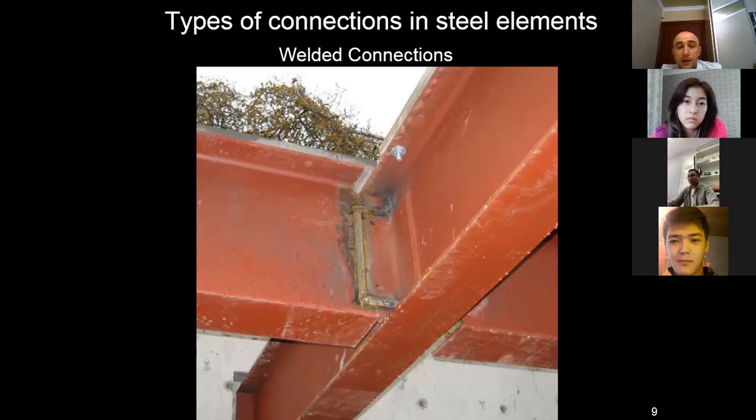By the way, the inspection of the welds is more difficult, and hence repair works are also not very easy. That's a disadvantage of welding. Variability actually exists in the quality of weld. It's according to the professionalism of the erector.